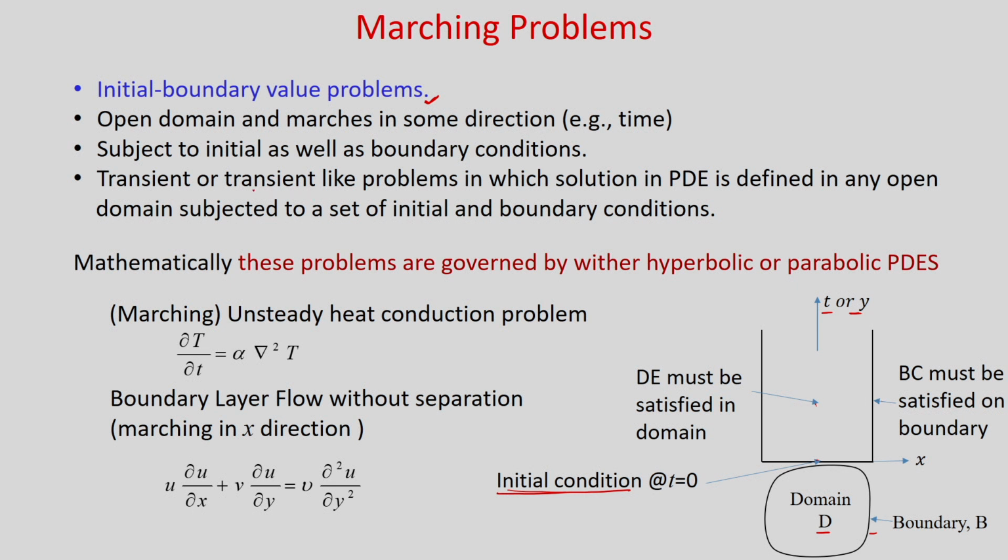These are propagation or propagation-like problems, in which the solution of the PDE is defined in an open domain subjected to a set of initial and boundary conditions. Mathematically these problems are governed by hyperbolic or parabolic partial differential equations. You can have an example like the unsteady heat conduction equation, del T by del t is equal to alpha grad square T.